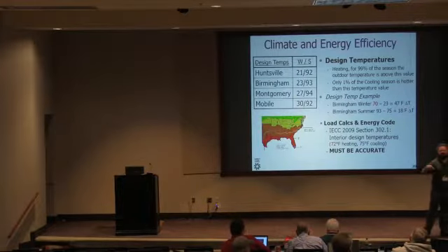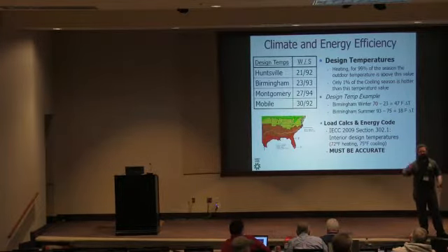I'm going to foam the roof line, and I'm going to do a blower door test afterwards. And there's actually a way you can determine how much additional ventilation you need. In my world, I would ventilate to ASHRAE 62 anyway, and I would put the house under slightly positive pressure, which could help me mitigate soil gas issues. But it is potentially possible that you could make a house tighter and then have a greater radon level.